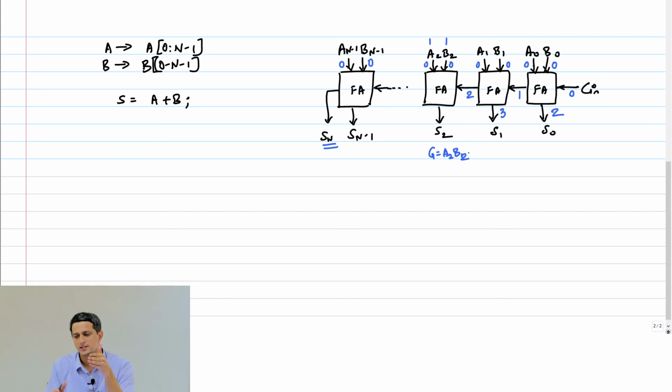So this is the reason we are trying to create these intermediate signals, just to make a decision on whether you need to wait for the carry or not. Here we are not making a decision, we are just evaluating it. Later you will see that I can make a decision based on this information. Similarly, the propagate here is A2 XOR B2. If that happens to be 1, that means the carry has to be propagated, which means that you have to wait for that carry to come.